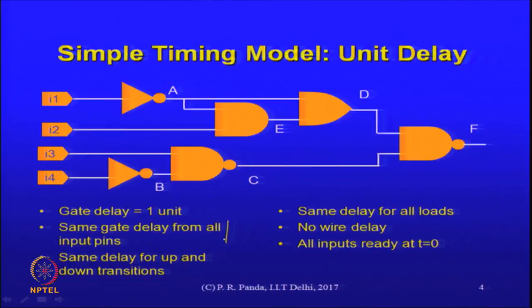The reality is that this delay might be different in general from that delay. From delay means an input changes and how much time later the output changes. It depends on what the circuit is doing. The result of one input changing might propagate much faster to the output than some other input changing, in general, of course.